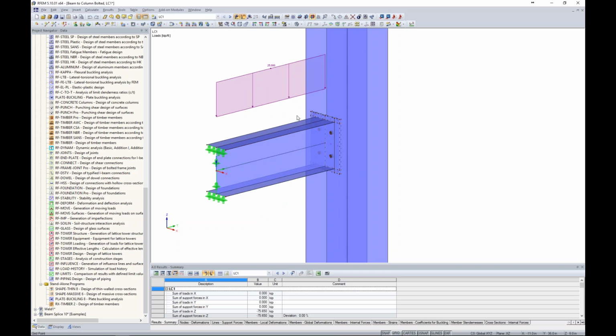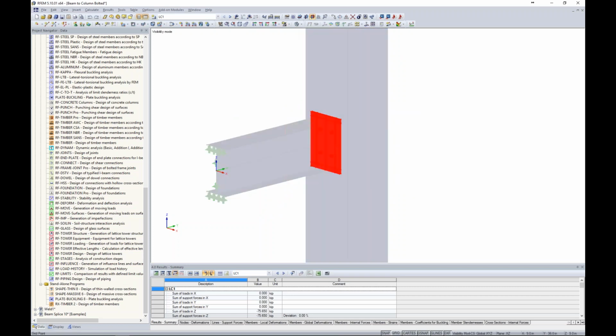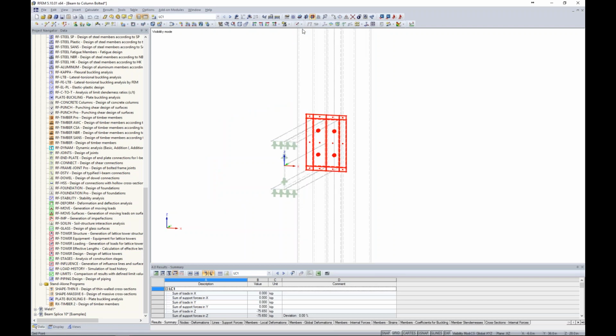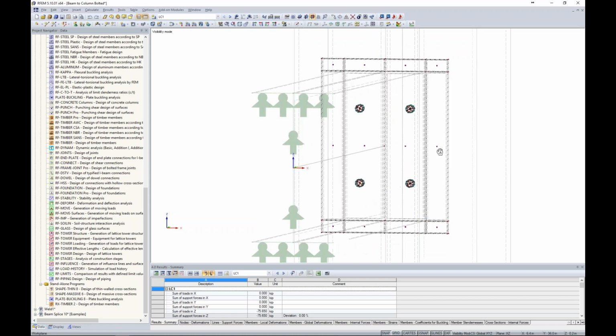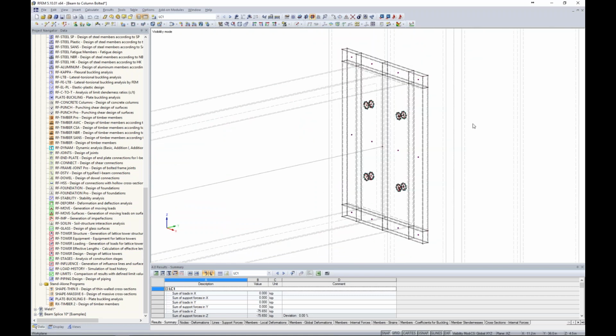Again, we don't have symmetry on the left and right-hand side of this plate anymore. So making a visibility view here based on my plate only, and maybe I turn this into wireframe, and we'll change around the viewpoint here. Here is my plate looking into the page of my beam. You'll notice that I have 4 contact solids defined at the top, 4 in the middle, and 4 at the bottom. The reason for this is simply because I didn't have so much symmetry like we did in our last model, so I had to create these smaller contact solids in order to meet the requirements.